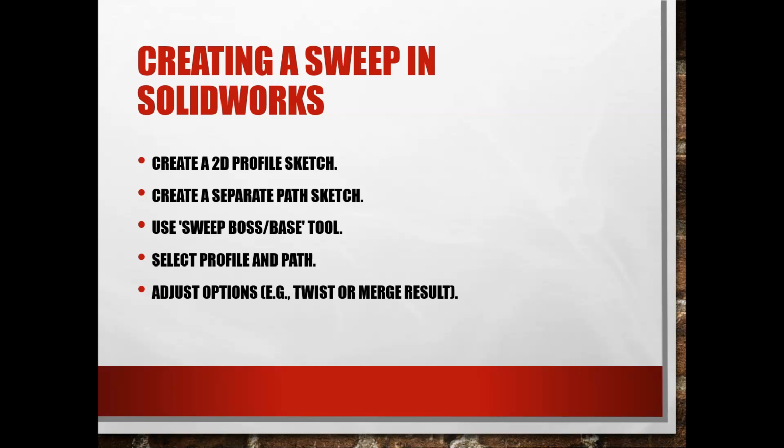Now, I'm not going to give you any examples, or I don't think I have any examples, of ones that have any twist or things of that nature, but we will discuss what the merge result is in some of those examples. The one that's right off the top of my head is when we create a drill bit, you're going to see that there is an option to merge the results. And in SolidWorks, it's nothing more than just a checkbox.